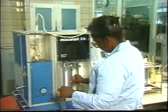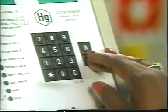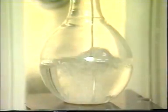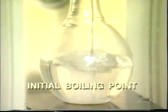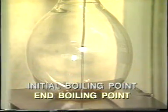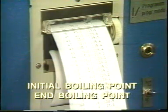One way to analyze the composition of a product is to perform a laboratory distillation test. This test is performed by heating a liquid sample and then collecting the condensed vapors. The temperature at which the first drop of condensate is collected is called the initial boiling point. The end boiling point, or end point, is the temperature recorded when the last drop of liquid in the container vaporizes. A range of temperatures between the initial boiling point and the end point determines the product's boiling range.